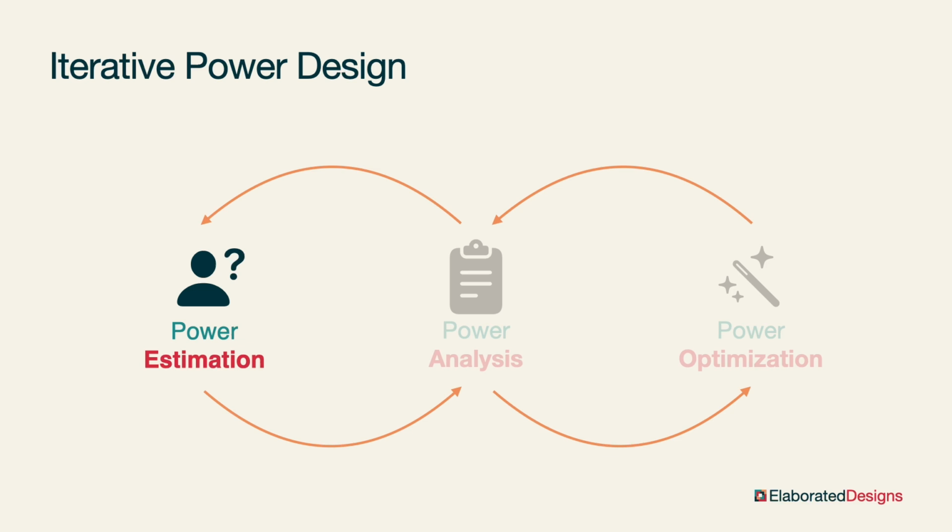At this point, we might notice that we have exceeded the power budget for a portion of our design, so we can run power optimization on that section to try to bring the power down. Next, we can generate a power report for the optimized design to confirm that we are back within budget. From there, we can run power optimization for other critical sections or further refine our initial estimate with the newest power report.